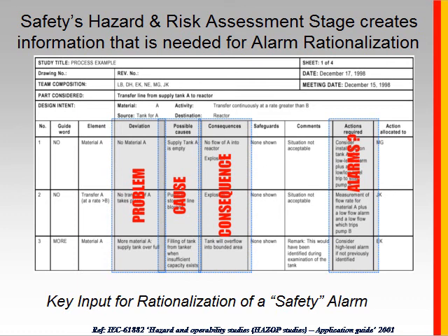So for example, most control systems provide 5, 6, 7, or 8 alarm types for a simple analog indicator. So you may have high, high-high, low, low-low, rate of change, bad quality, etc. In many projects, people would enable all those alarms. They're free, right? No cost to enable all those alarms. Well, when it comes to alarm management, more is not better. Many people will do that.